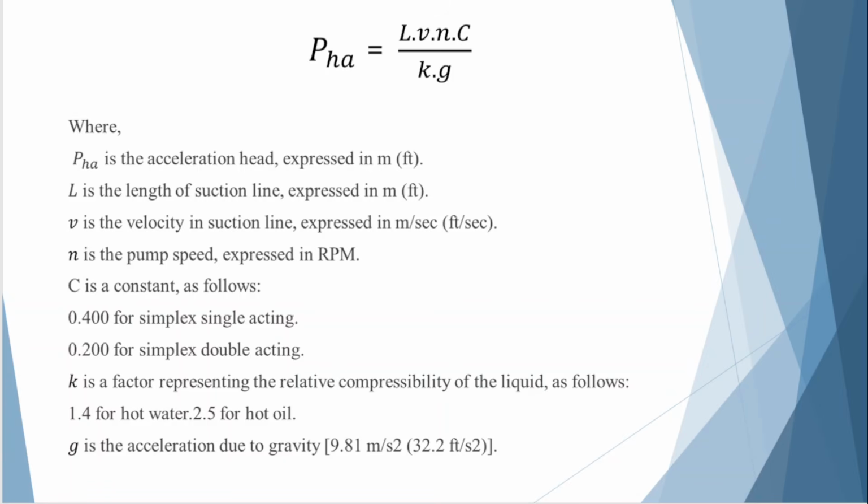This calculation helps verify that sufficient inlet pressure is available and ensures that the pump operates safely without cavitation, excessive pressure pulsations, or vibration. Although this is a simplified equation, it serves as an excellent first check during the design stage and helps engineers identify potential hydraulic issues before the system is built.